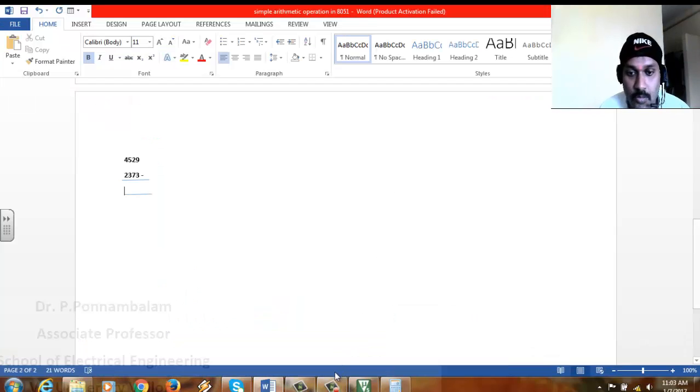Okay, now we'll go for 16-bit subtraction. In 16-bit subtraction, we'll assume these are the numbers that we are going to subtract: 4529 minus 2373. So 29 and 73 have to be subtracted first, and in this case it will get a borrow, which will be carried over to the next one. The borrow that has been carried over will be subtracted again.